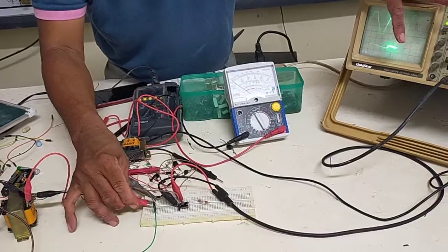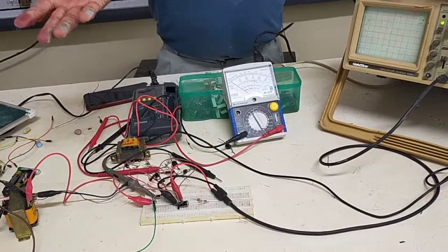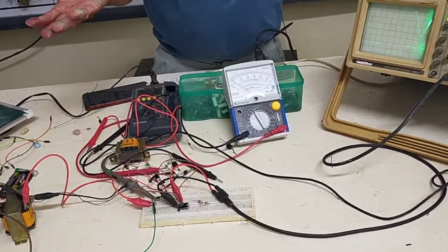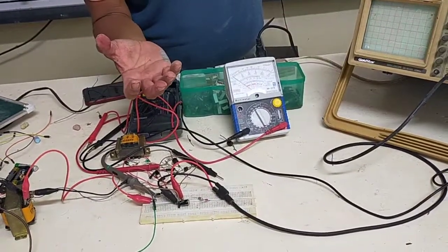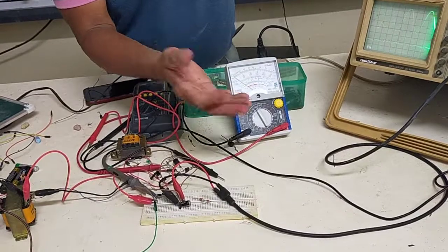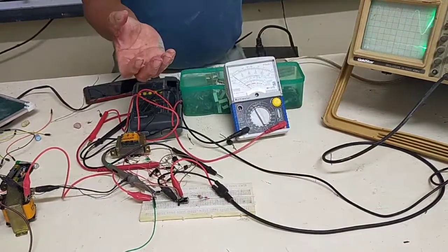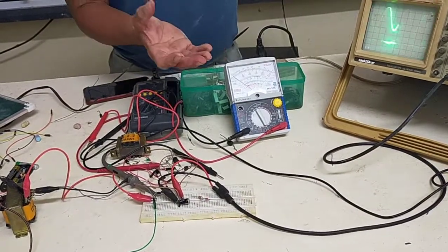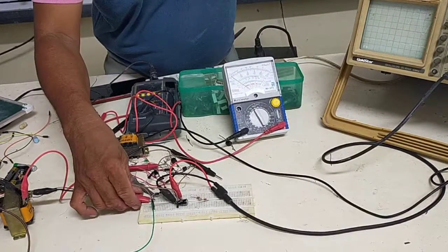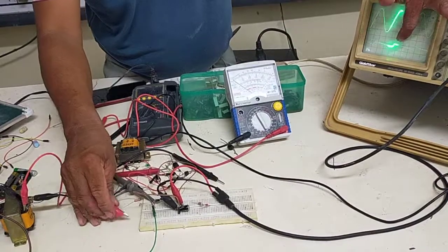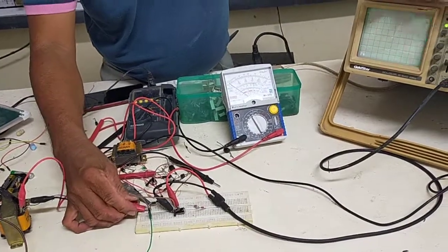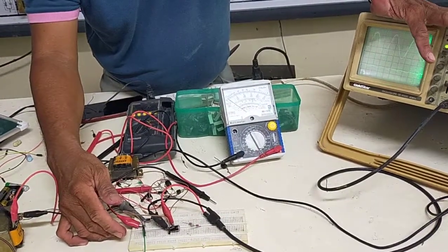So, when it is supplied to a certain amplifier sound system, the sound is better than half wave because the sound now has less distortion for the full wave compared to the half wave, which has a bigger variation of voltage, around 2 volts. But with full wave, it is refined, it is 1 volt.